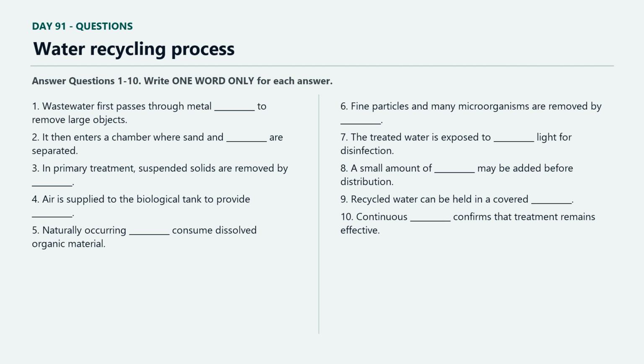Continuous monitoring measures variables such as flow, pressure, cloudiness, disinfectant level, and lamp performance. Automatic alarms warn operators when a result moves outside its permitted range. The plant may divert water away from the finished supply until the cause is identified and treatment is restored.